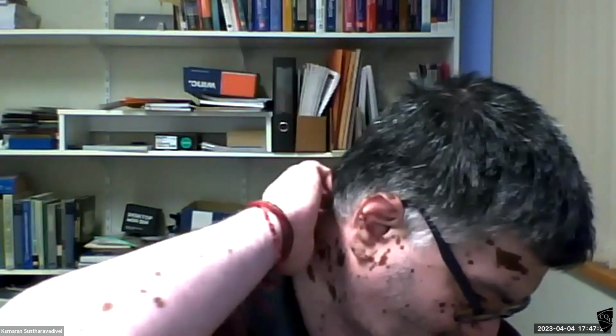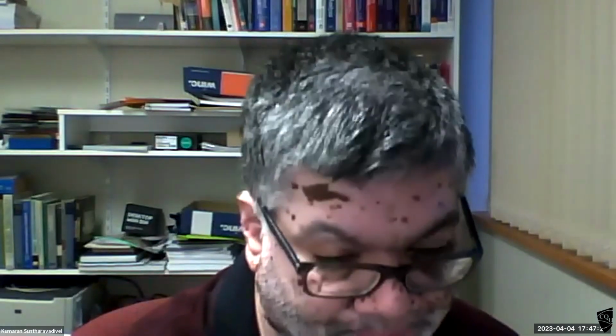That should be okay. If the crack width is larger than 0.1, you need additional steel. So you need to increase the steel a little bit and see whether you can get it to 0.1 or less. Okay, is it clear? So don't repeat all the calculations. Read the question carefully. If it is not clear, just let me know.